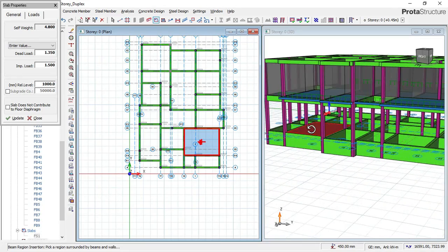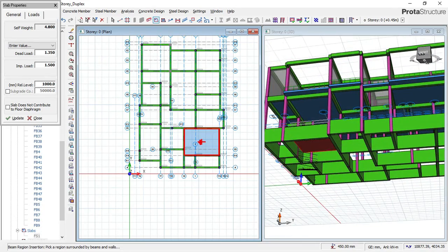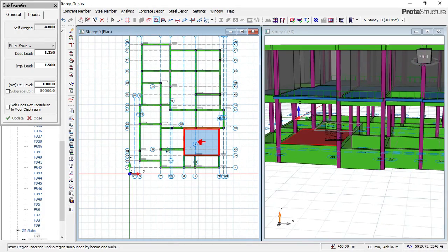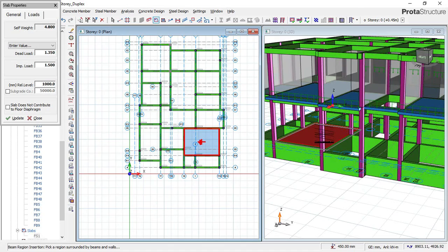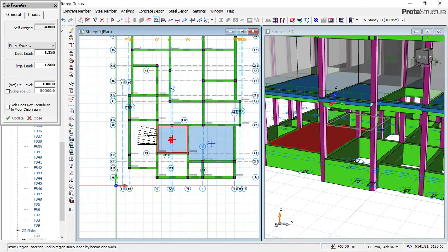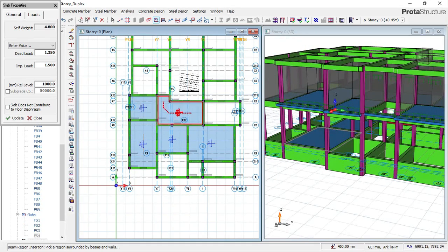Now you can see that there is a space between the bottom of the beam and the slab. There's a depth of space of 1 meter. This space will be filled with sharp sand, and then we will use a polythene material which will serve as a waterproofing membrane. Right now I begin to insert my slabs. You can see how the slab is being filled in. I begin to insert my slab in all my panels.